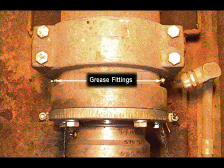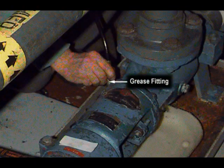Problem: the bearing housing becomes hot, 160 degrees Fahrenheit, 70 degrees Celsius, or more. Probable cause: the bearings have been over-lubricated. For this, remove the relief plugs in the bearing and run the pump for a short time. Then replace the plugs. Or, the bearings may need grease. Add grease through the fitting.